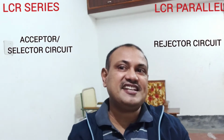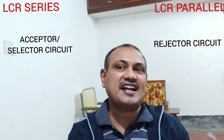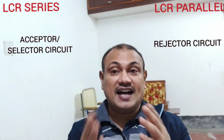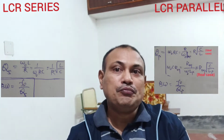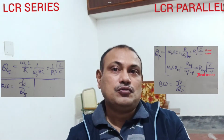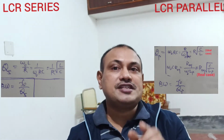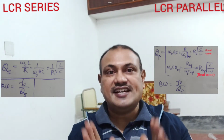LCR series acts as an acceptor or a selector circuit, but LCR parallel acts as a rejector circuit. The quality factor of LCR series is equal to omega 0 L upon R, which is equal to 1 upon omega 0 RC, that is equal to 1 upon R times square root of L by C. But in case of parallel, you have omega 0 RC, which is equal to R upon omega 0 L, that is equal to R times square root of C by L for an ideal LCR parallel circuit.